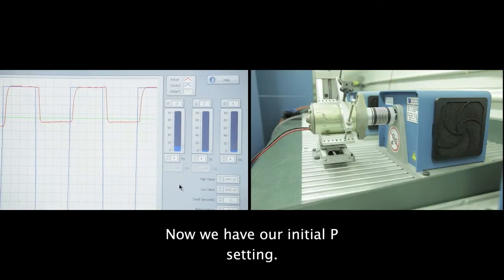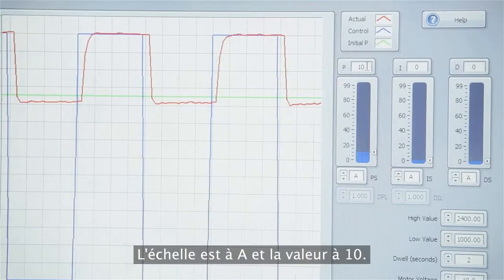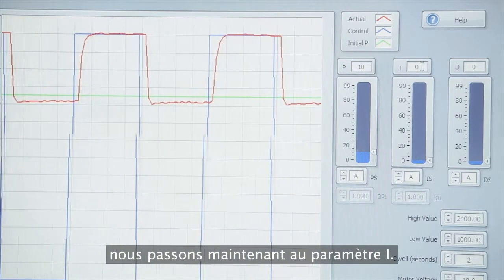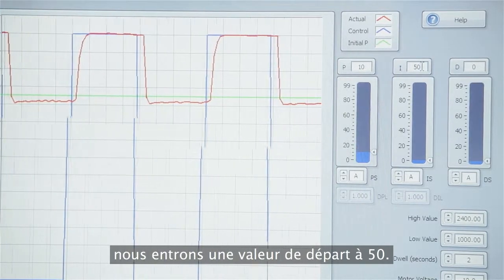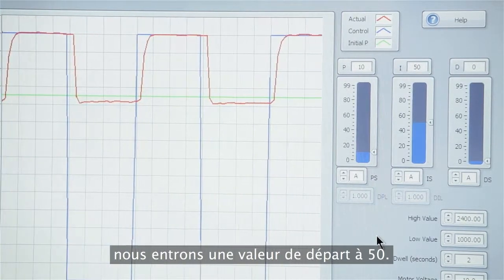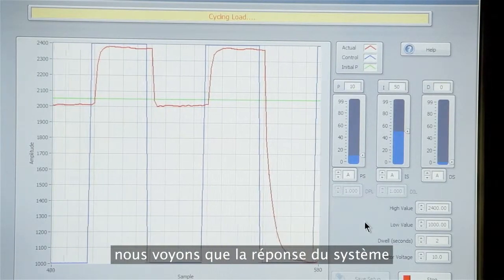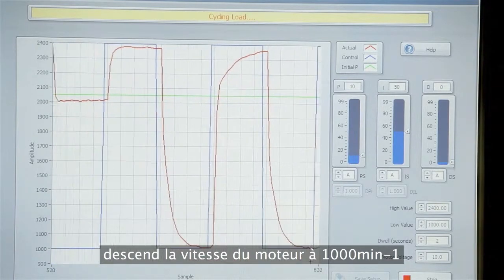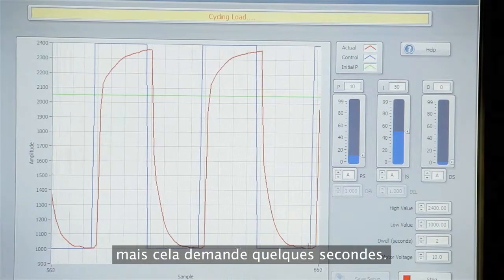So now we have our initial P setting. The scale is A, the value is 10. Now we go over to our I term and enter a starting value of 50. And you'll see that the system response is bringing the motor down to 1000 RPM, but it's taking a couple of seconds to get there.